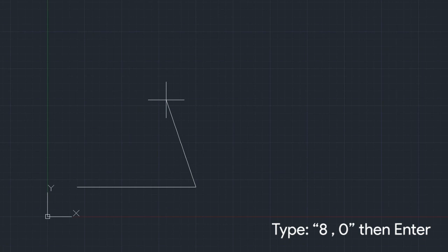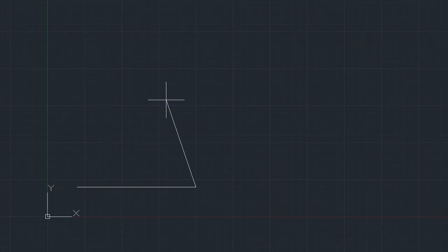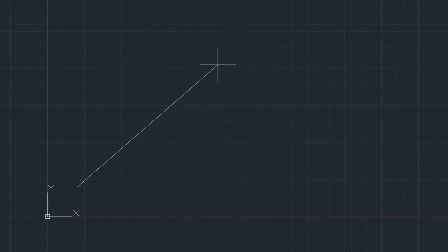So, na straight na siya nga horizontal line because it is assumed that our origin is located at the first point. So, mao na itong relative coordinate. We also have absolute coordinate. Sige, ako ragi undo. Ako ragi undo ha, Control Z. Let's have this absolute coordinate na po.